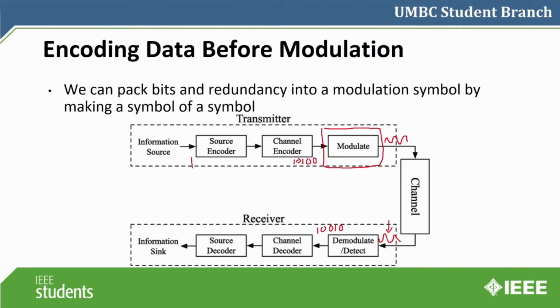You can also do encoding. And encoding is what we learn with Hamming codes and CRC codes. And these are how you add error detection and correction. So what that means is I'm adding parity bits. I am modifying the data so that it's less likely to get an error. And if I get an error, that I can fix it instead of having to just retransmit until the error goes away. But we're not going to get into encoding because that's a little advanced for this meeting.